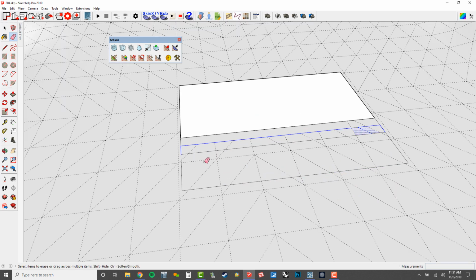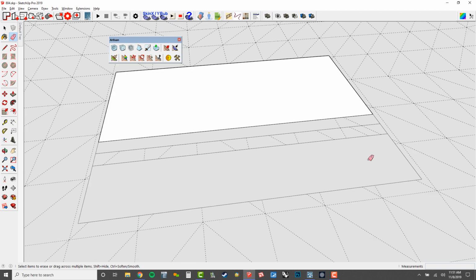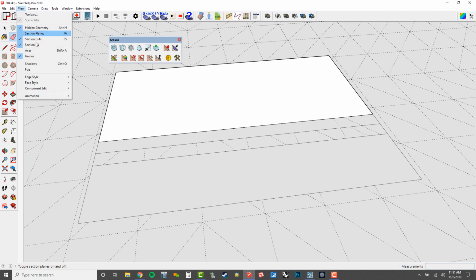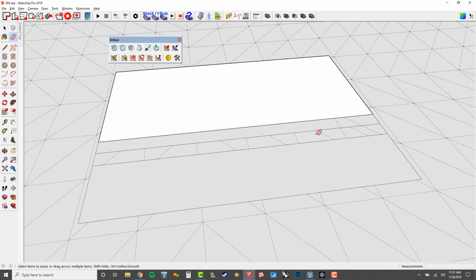and let's just make a reflecting pool out in front. And so to clean this up a bit and let me work on it with the tools I want to use, I'm just going to clean up some of these hidden lines. So to see all of your hidden geometry, that's under View and then Hidden Geometry. Again, that's a keyboard shortcut I use all the time, is Alt-H.